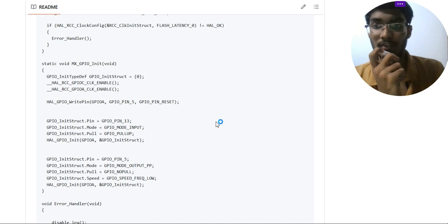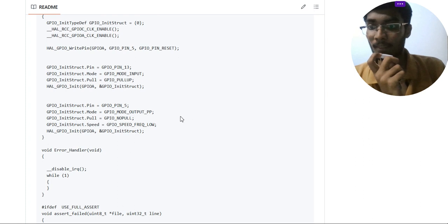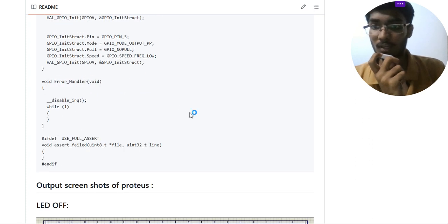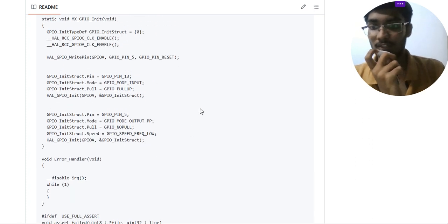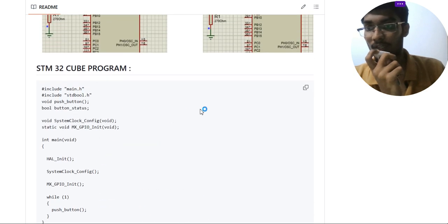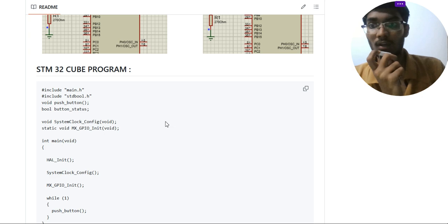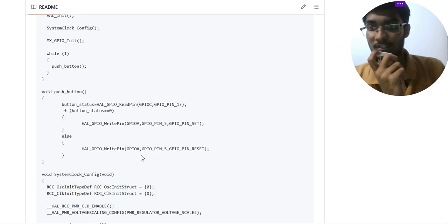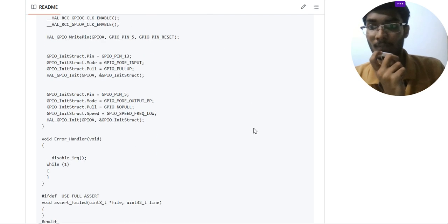When it is clicked, it will light on. Otherwise, it will reset to the 1 state. Button state is equal to 1. When it is pressed, it will update to 0 and the light will be on. That's all we deal with in this program, because the remaining program will be available in the STM32 program. This is the main function we have studied.